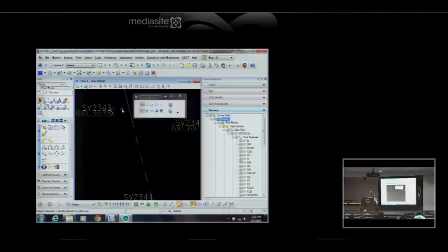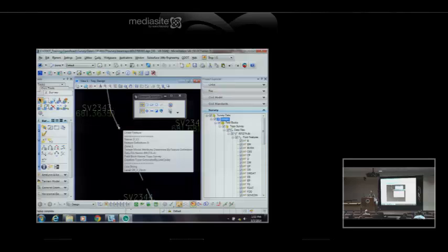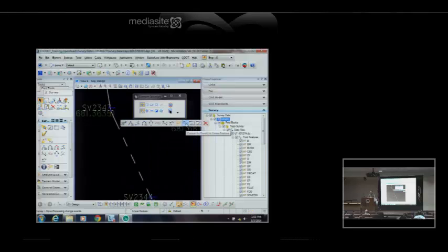So if I want to make this a point list chain under selected, I have to convert it to a point list feature. Now that it's converted to a point list feature, and in the ODOT standards we made the dynamic chain the default, when I select it I have a little different tool set. I didn't talk about what tools popped up, but I've got the typical stuff you'd want: move a point, slide it along it, insert a point, different things.